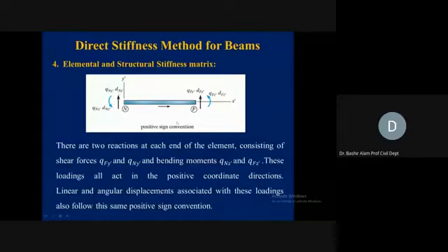So now at the far end again, Q is for the action produced and D is for the displacement produced. With the Y subscript, it is showing the translation, or the shear now. QFY is now the shear produced at the far end in the Y direction, and D is the displacement produced at the far end in the Y direction.